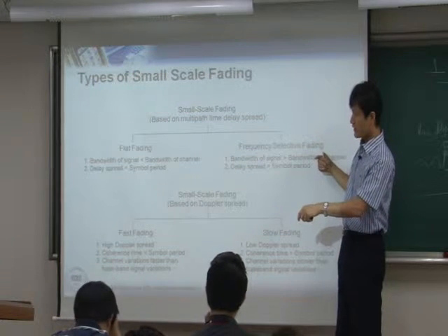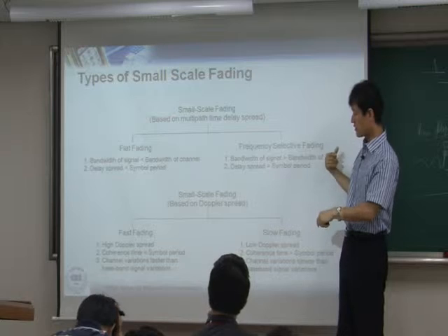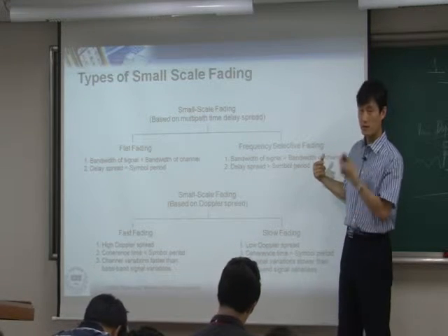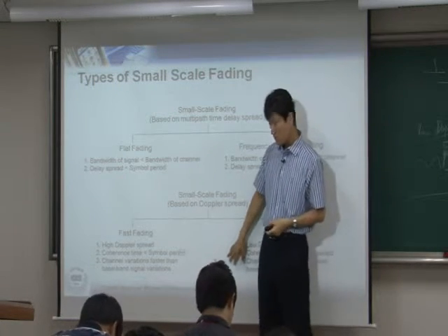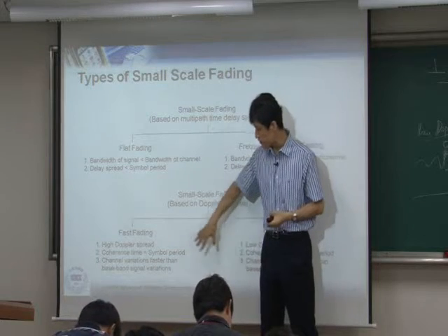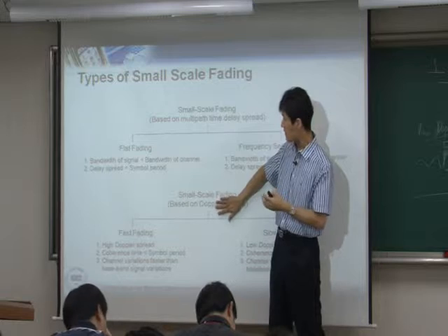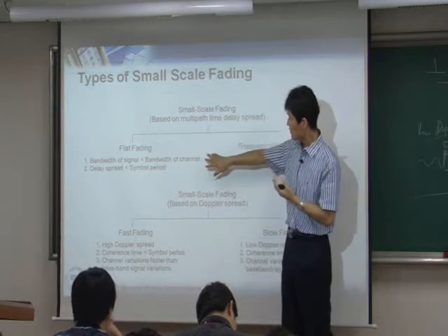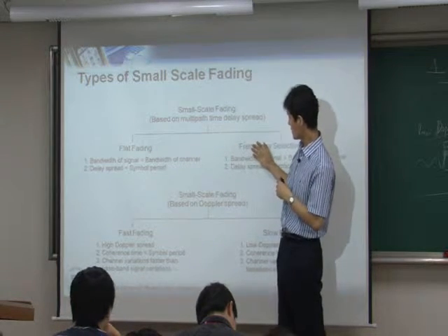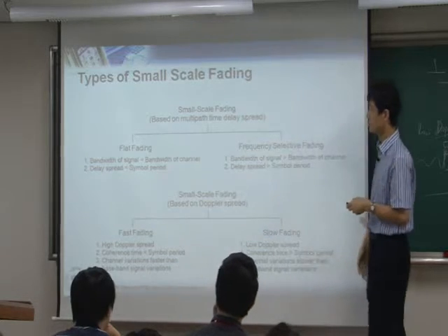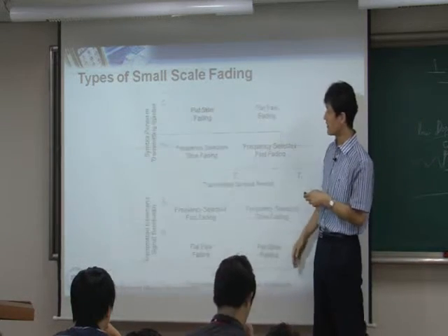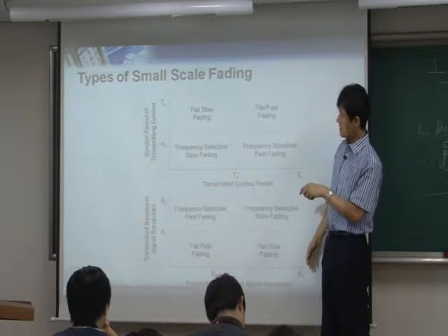Whether you have fast fading or slow fading depends on Doppler. You see what I'm saying? So whether it's fast or slow depends on the Doppler frequency. Whether you have flat fading or frequency selective fading depends on the delay spread.